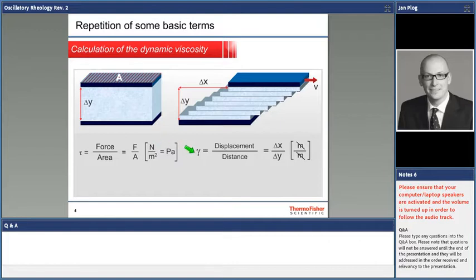The deformation that I'm going to talk about later on when we go into oscillation is a parameter that just describes a displacement over the distance. So we call it deformation. Some people call it strain. Okay. The problem with a deformation is that it is, in a laminar flow field like this, not constant. Okay, the deformation is at max at the movable plate.